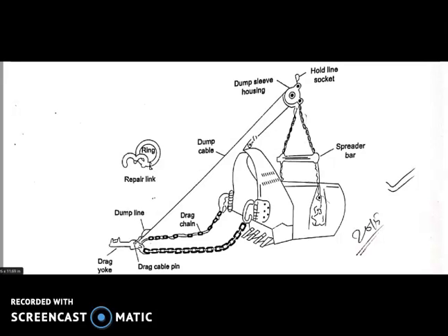Material is fed to the bucket through the front open side, and is discharged by overturning the bucket at the dumping point. Buckets with perforated walls are also available in some designs. The digging teeth of the bucket are also of a replaceable type.